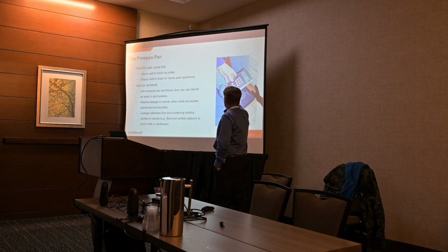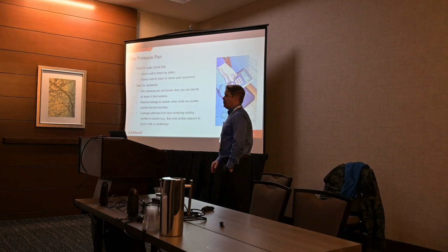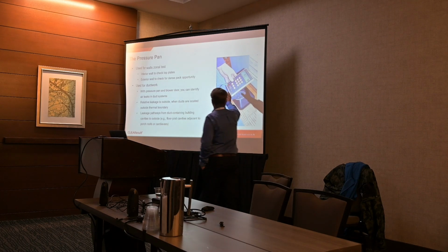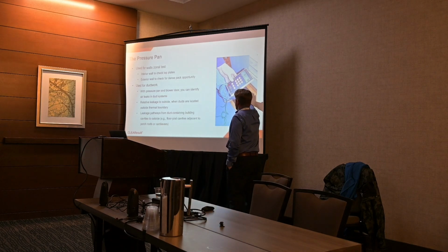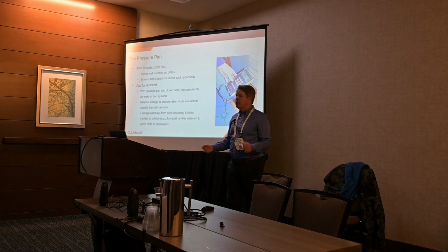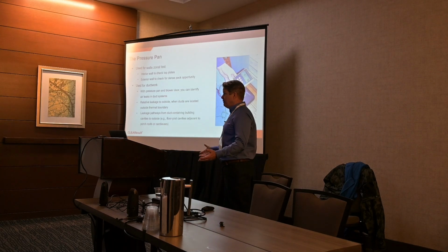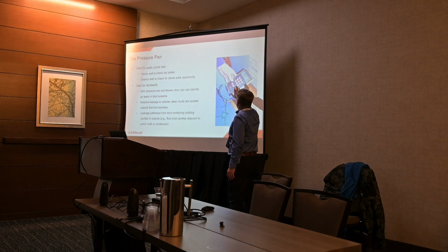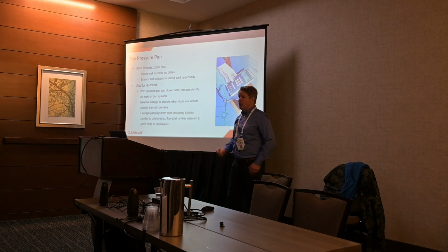Okay? You can also do that on the exterior walls to see whether or not it's a good candidate for dense packing. It can be used on ductwork, like you can see this guy doing right here. So once again, push the ducts as outside as you can, open up the basement door, that sort of thing, so the ducts are outside, pressure-wise. And then the same, what he's doing right here, pressure gauge, and put it over the supply. And with the ducts, we're looking for a really tight number, right?